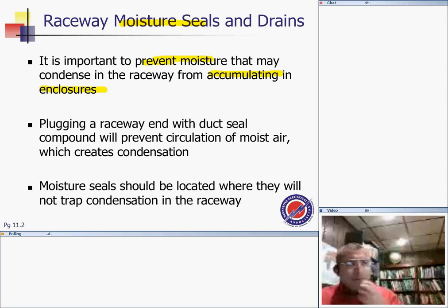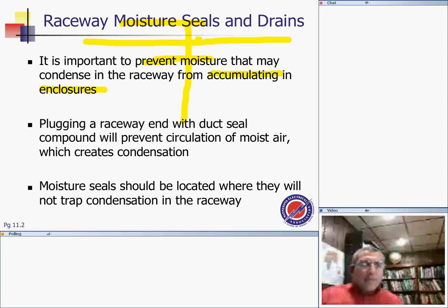So we seal the conduits, especially when a conduit comes from outside to the inside. A couple of days it's going to be minus 13 outside, and inside, in most applications, you're going to find 72. With that temperature difference there will be condensation. You prevent that condensation, guys, and the dripping of water right above your equipment.